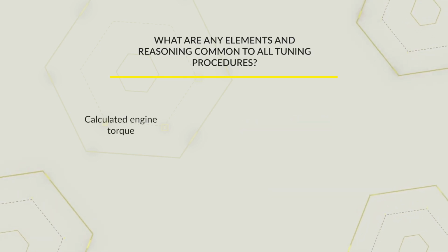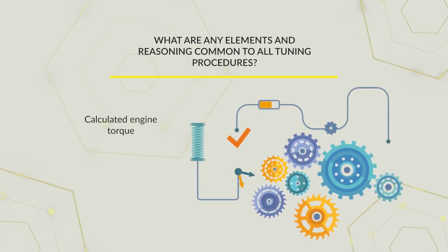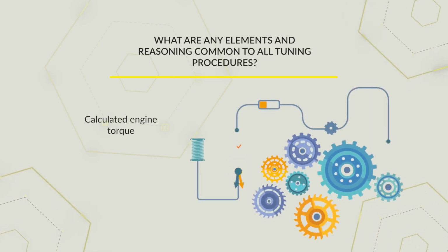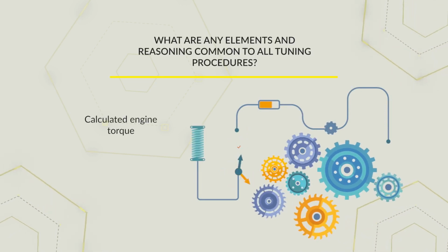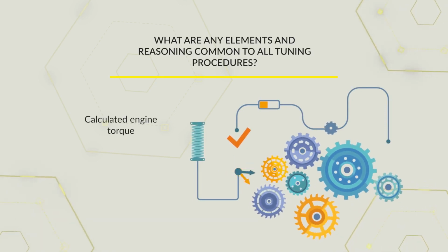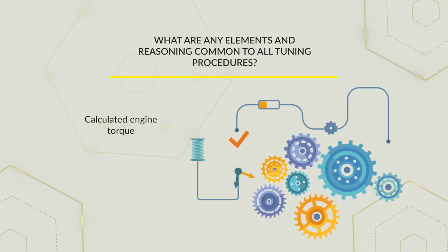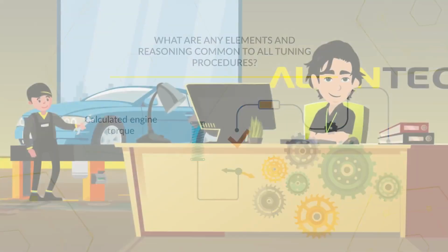Calculated engine torque. It is always a good idea during diagnosis to check whether the torque defined in the file written on the control unit is actually developed. This can also be considered as a parameter that defines the quality of our tuning.